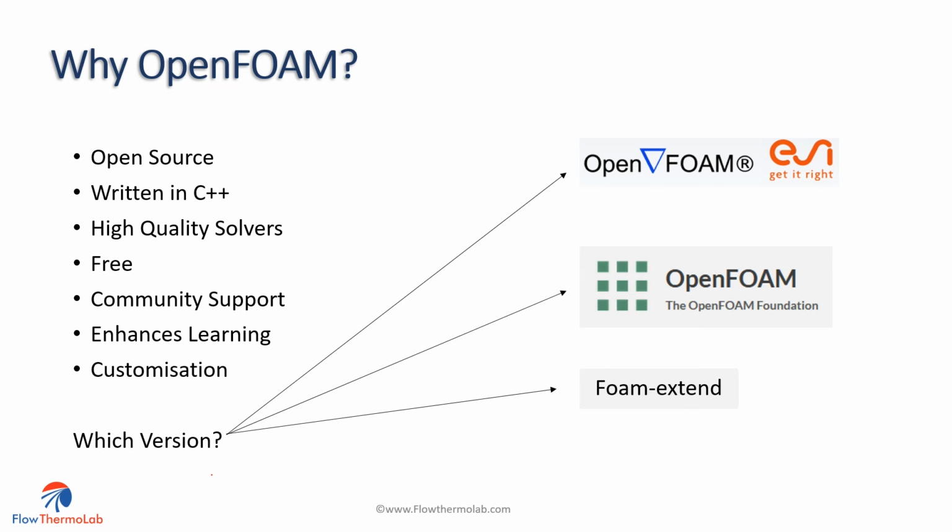The Foam Extend version can be quite interesting to look at, because there are certain things that are unique to this version. So, for example, it actually has a fully working coupled solver for pressure velocity coupling instead of using a segregated approach, which is really interesting. But you need to be careful because it can fall quite behind in developments versus the other 2 forks, and may lack improvements that we see in the latest version of, say, the ESI build. And as such, the source code can end up being quite different in certain areas and quite confusing to compare if you have them side by side.